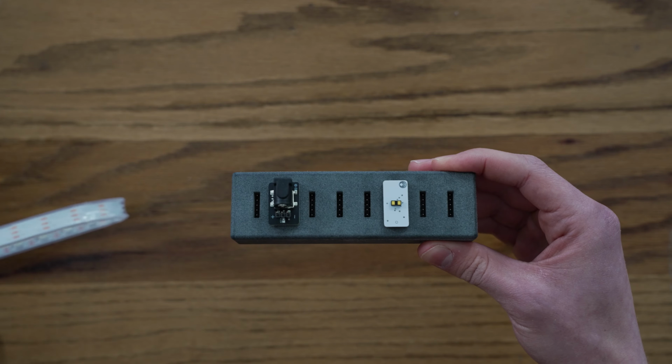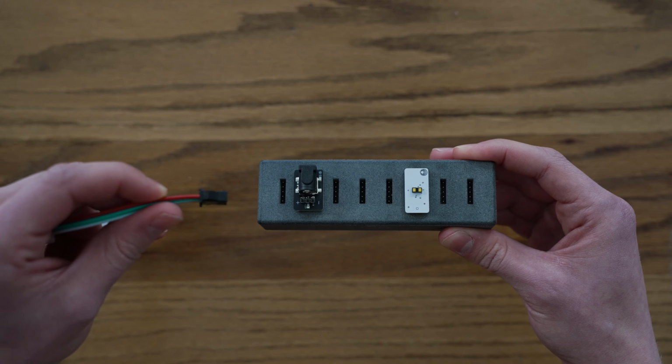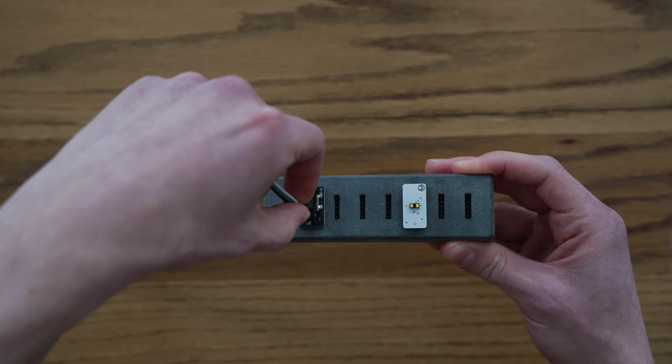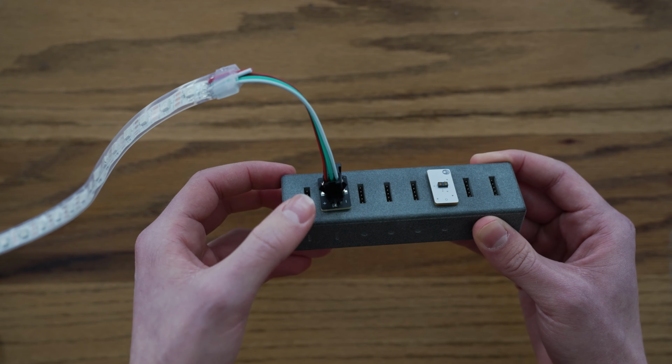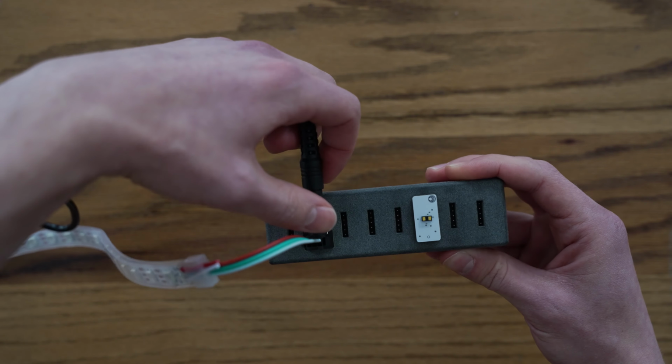On the LED strip we are using, this corresponds to the red power wire. Use the plus icon as a reference to attach and line up the LED strip. Double check that it is in correctly, and then plug in the power supply to the barrel jack. We are using port 7 for the LED strip since it is near the USB-C port, which will make any cable management simpler.